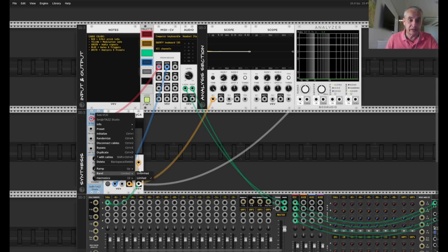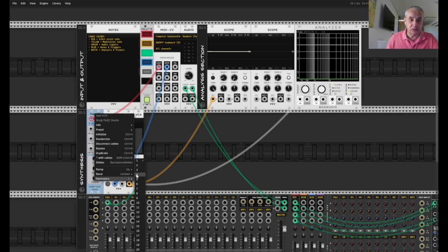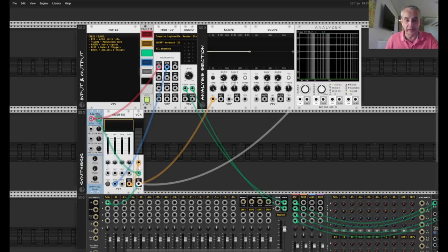So if I just select one harmonic, it's actually only the bass note, which is actually just a sine. So you can see we have a perfect sine wave, and it also sounds pretty dull and not very rich in tone, because it's just a single sine wave which can be reproduced perfectly correct without any aliasing. Now if I would go to 2 harmonics, it would mean that a second sine wave of double the frequency but with a different volume level is added on top.